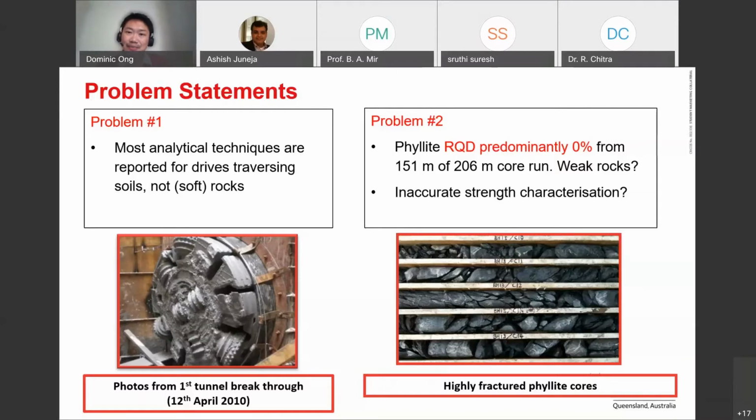But the issue here also is, does that mean that your rock mass in the ground has no strength? Because you see that the recorded result is RQD 0. If the rock mass is in compression, confined by the confining stress, do you expect to see these fissures open up? So this gives us another perspective of the strength. On record, on paper, it is RQD 0, but in real life, as you try to tunnel through this kind of material, the answer is that you do not get 0 strength. You have actually quite relatively high strength. So again, whatever we got on paper is actually not representative of the ground, and this gave the contractor initially a bit of a challenge in characterizing the ground. Okay, so it has a strength representation in this case.